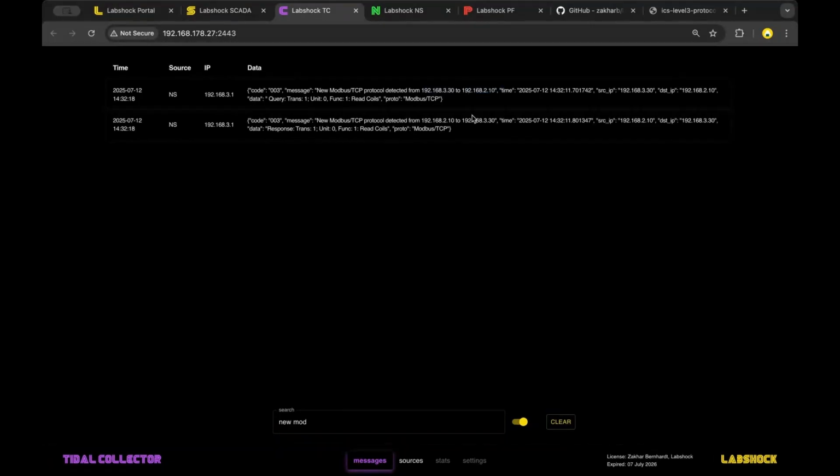So these are new communications being created in your critical network segments, they are logged, and you can extract this data: something from function code 1, something reading coils from Modbus TCP at this time. This is the first step in how to monitor the network.